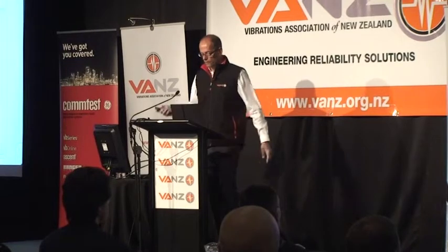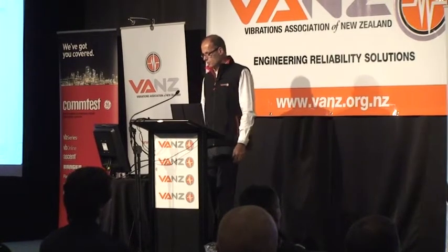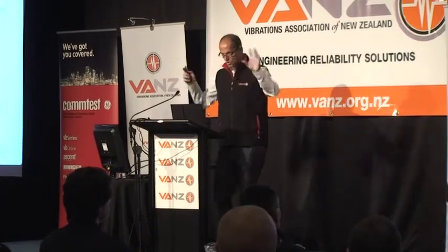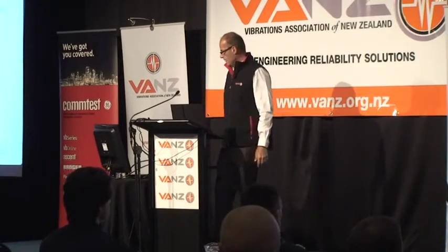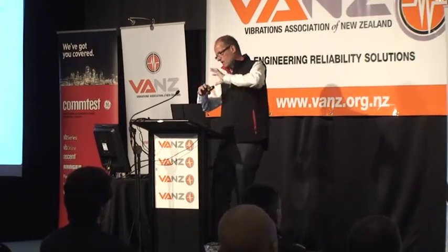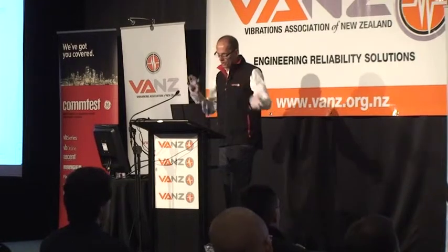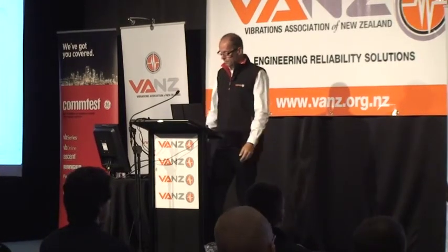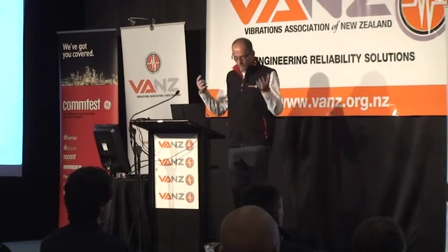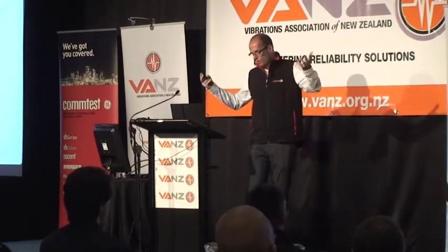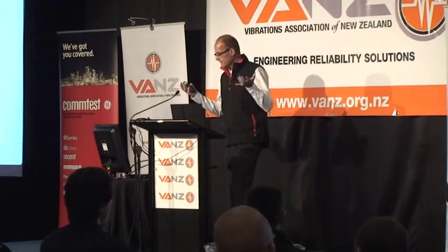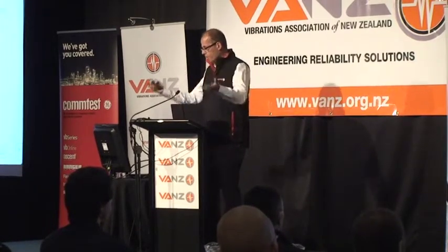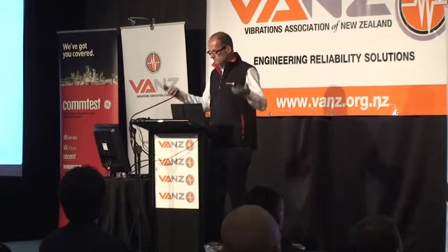That's occurring more frequently, and this is somewhere in between. So, you can detect all these things. We can use techniques that detect the stress waves and all of that. We can get a very early warning that the bearing has a problem. And so very quickly, just to prove that it worked, here is a spectrum from a machine with a bearing that has a problem.